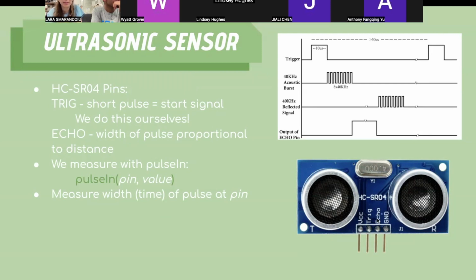And we have a built-in function within Arduino called pulseIn, and you can use this pulseIn function to do the easy measurement of how far something is using the ultrasonic sensor. We won't tell you everything about what it does because you can read the documentation for it, and that's a little challenge for you guys. Anything you want to say? No, not really. That's exactly how it works. You'll measure the time pretty much, and then you'll be able to figure out the distance from there. Okay, any questions from here?